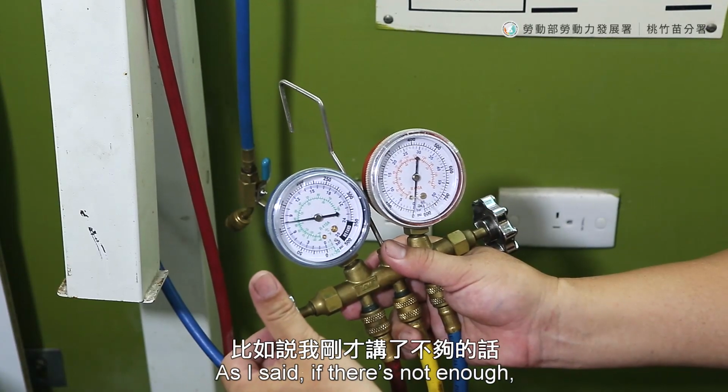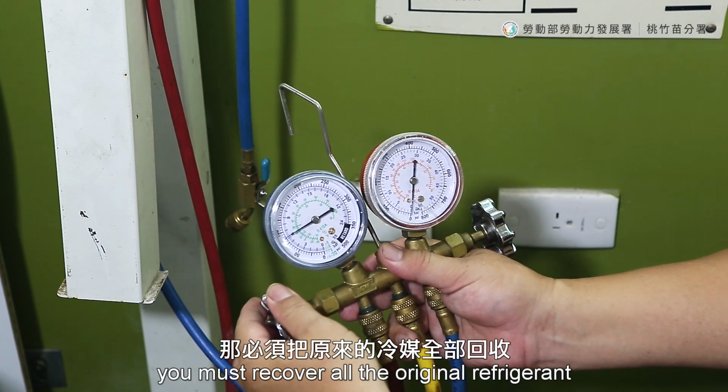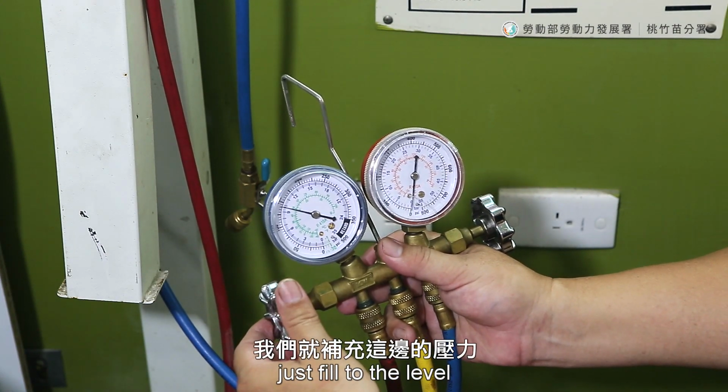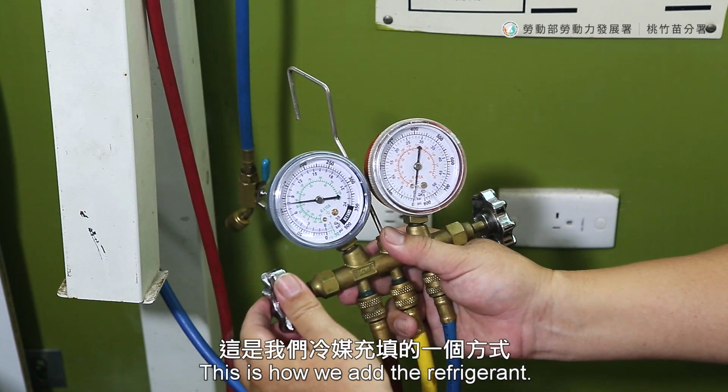As I said, if there's not enough, we need to add more. For an inverter split type AC, you must recover all the original refrigerant and use a fixed quantity method to ensure more accurate filling. For inverter AC, just fill to the level until the pressure reaches 120 to 130. This is how we add the refrigerant.